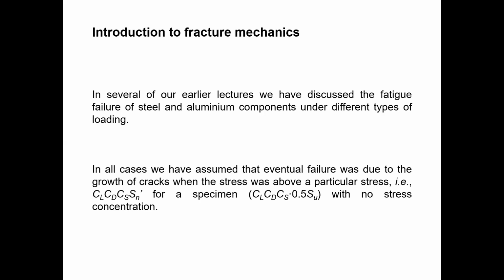Sometimes we make the stress concentration points artificially, and sometimes they occur automatically. Normally grooves and fillets are this kind of stress concentration point, so we try to avoid high stress concentration using smooth grooves and smooth fillets. If you introduce a notch, that is also an artificial crack.